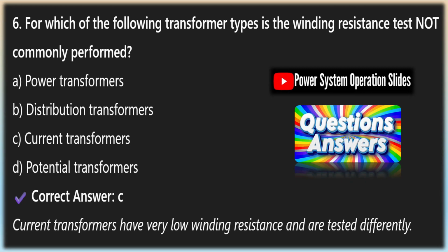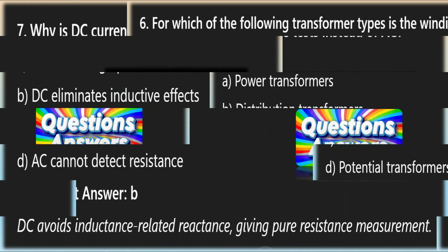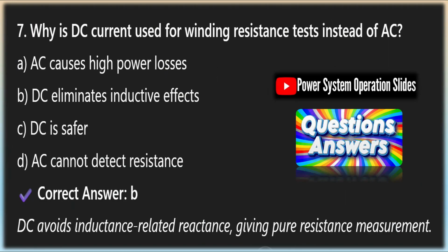Periodic resistance testing is most effective when combined with other diagnostic procedures including turns ratio analysis, excitation current assessment, and insulation integrity tests. Setting testing intervals based on transformer criticality, loading history, and operational records optimizes resources while managing risk. Risk-based planning can prioritize testing of high-importance units or transformers operating under abnormal stress patterns.